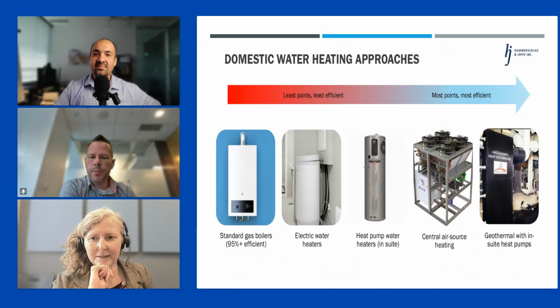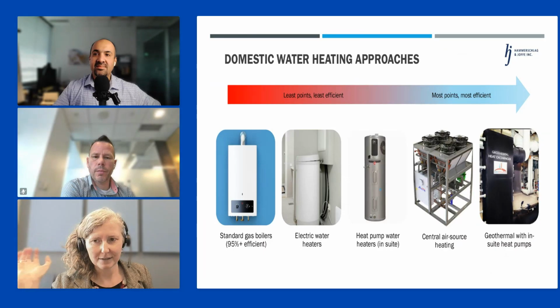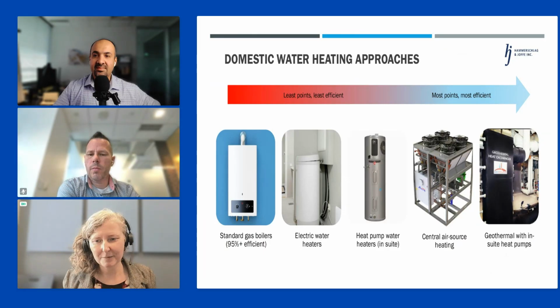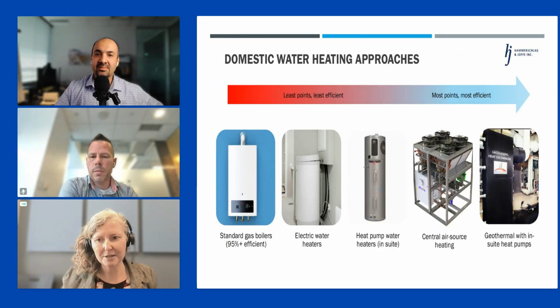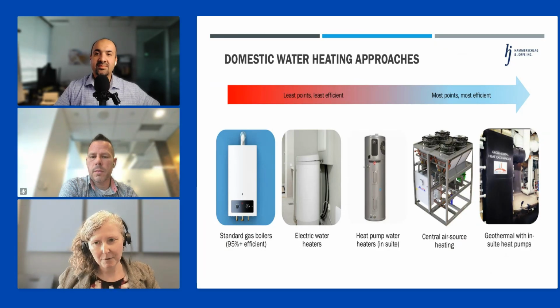All right. On the domestic water heating side, we see more variation. So in all our MLI Select programs, program participants have heat pumps for heating, and the great majority of them are using heat pumps for domestic water. So why is that? This is 20% of your overall building's energy use, especially as we dial down the building envelope portion of the consumption. So it's got a huge footprint in your overall energy picture, and being able to get that 3-to-1 energy efficiency really makes it easier for you to be able to implement the rest of your measures.